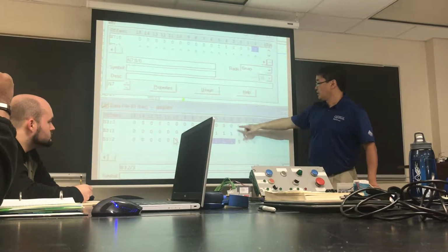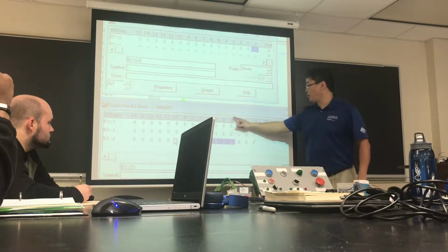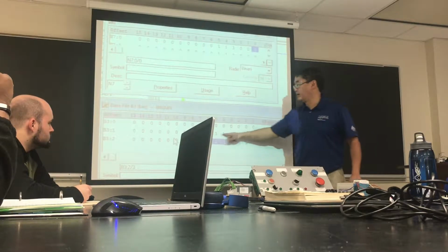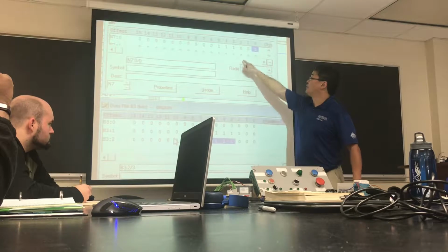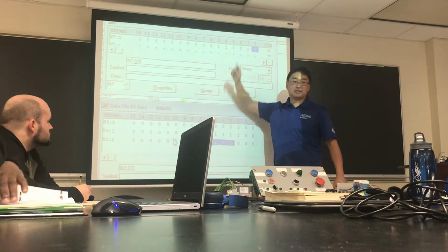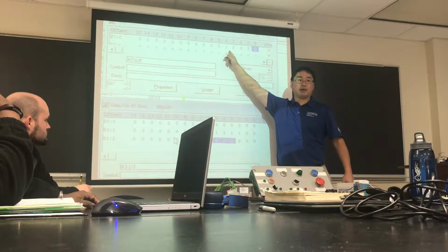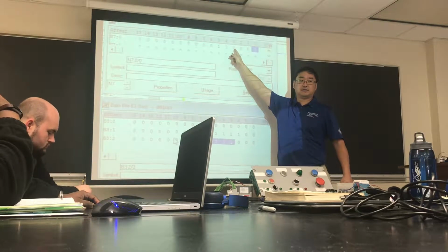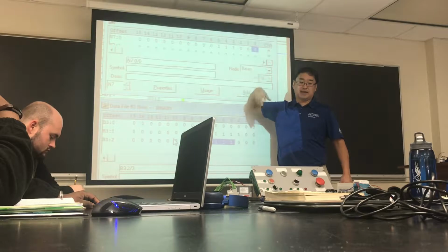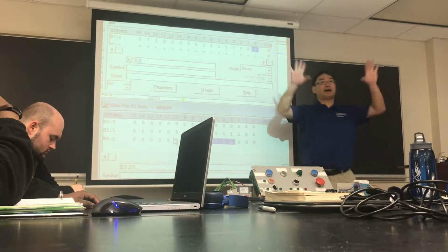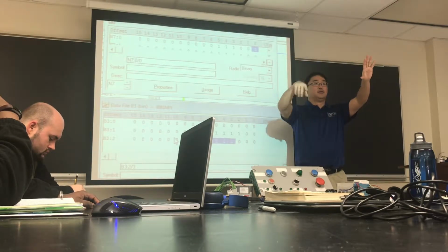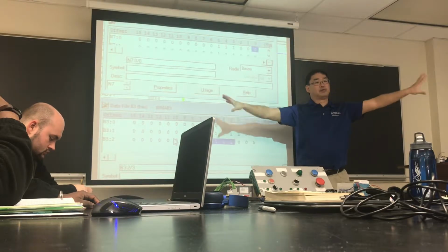But you'll notice I had 6, 5, 4, 3, and 2 turned on in my source. But the only 3 that got copied up to N70 are 5, 4, 3. Does that make sense? Why? Because that's how it works: it puts a mask over it and says only do the ones I tell you to do, and it ignores everything else.